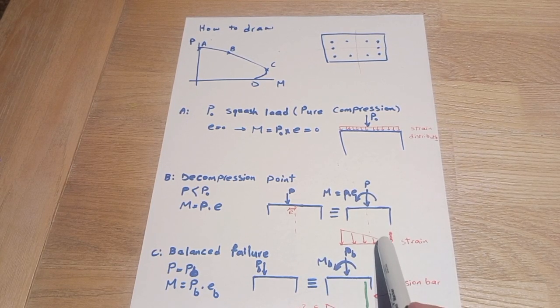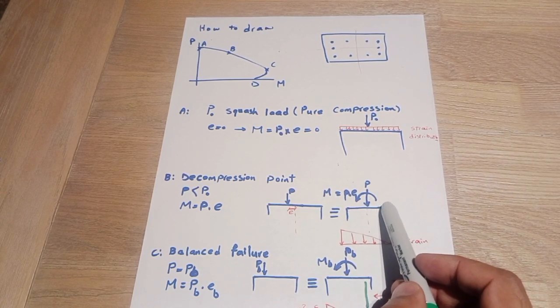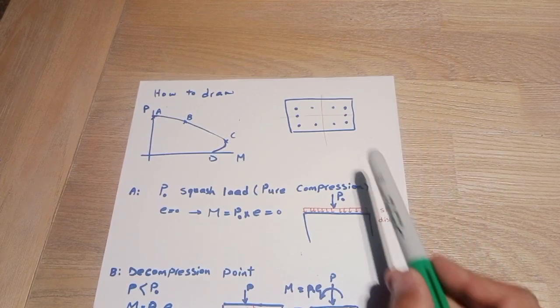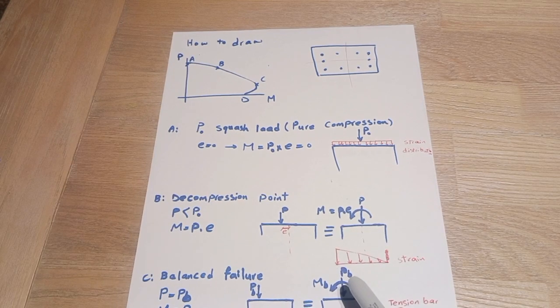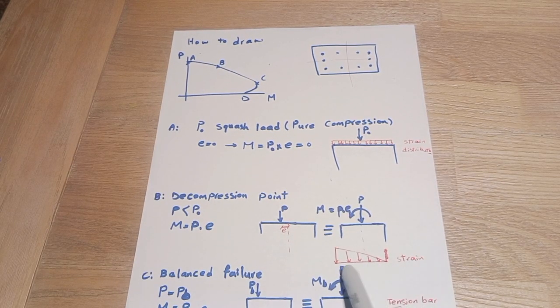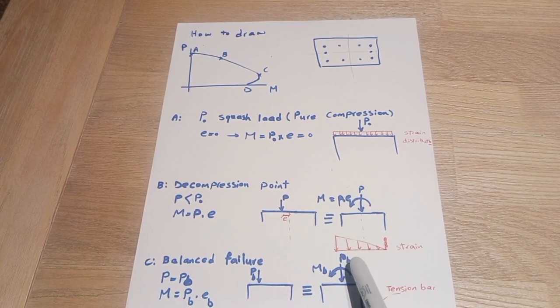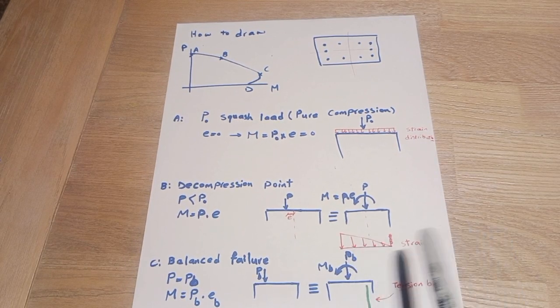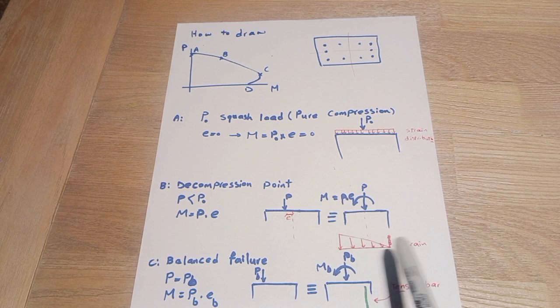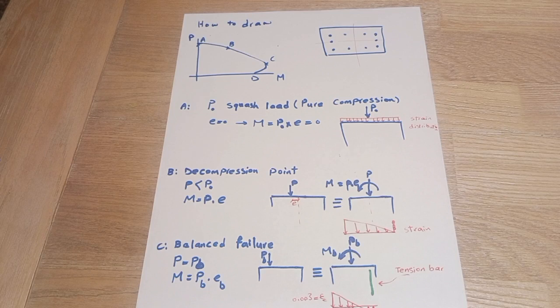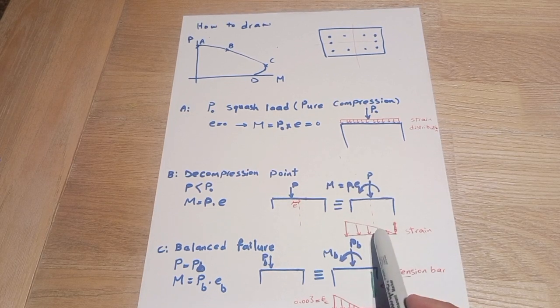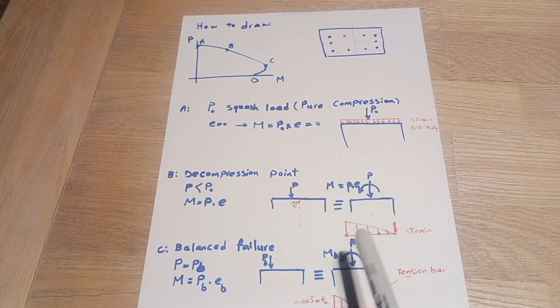And we can calculate the strain value for the steel layers that we have here. If you follow the section, we have 1, 2, 3, 4 layers of reinforcement, so we may have just 4 layers of strain for reinforcement. Especially for this one, we may have just yield reinforcement, but it's still okay to calculate. Based on strain values, for linear distribution of strain here, we can calculate the loads on each element of reinforcement bars and the compression side.